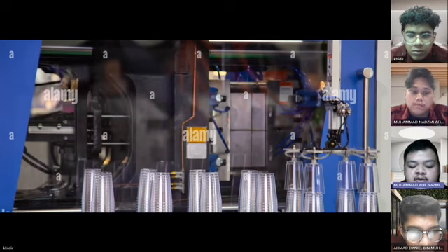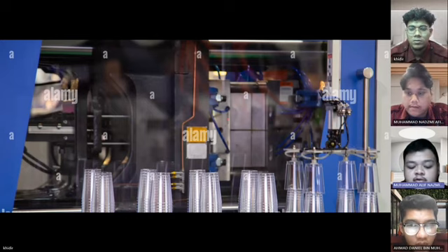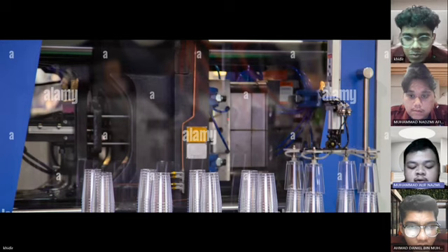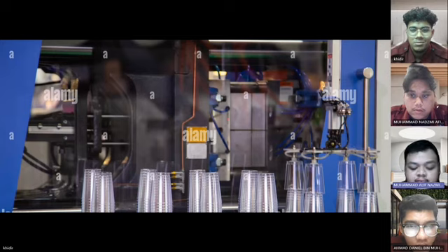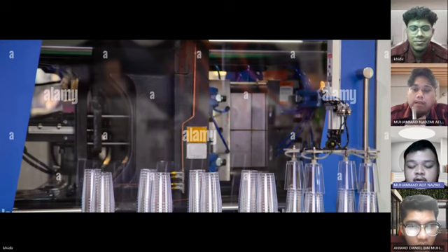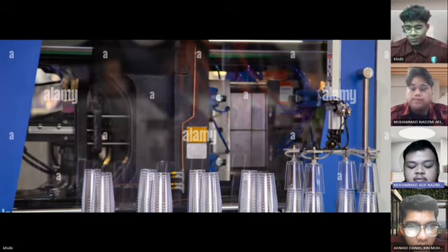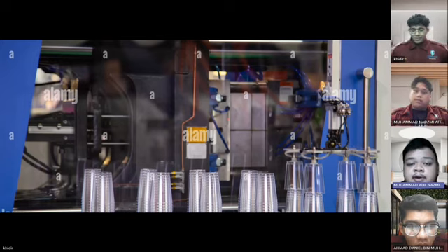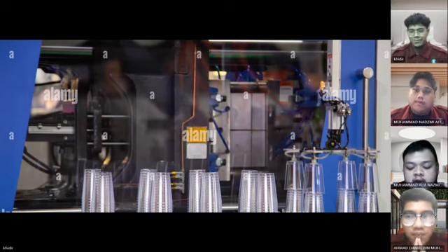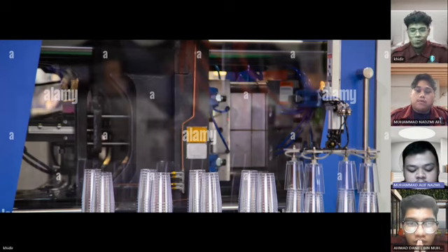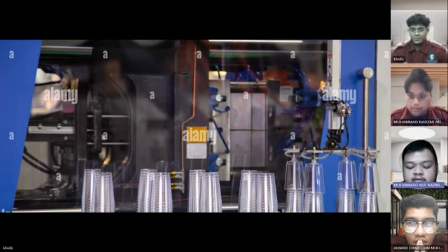The mold is mounted on a machine called an injection molding press, which closes the mold and applies pressure to keep it closed during the injection process. And then the plastic material is cooled inside the mold by circulating water and air through a channel in the mold. The cooling time depends on the size of the shape and the part of our product. Once the part has been cooled and solidified, the mold is opened and the part is ejected.